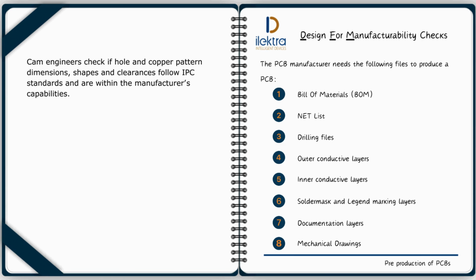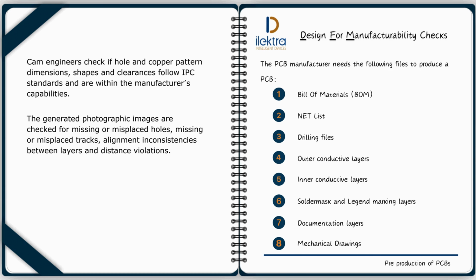Upon receiving those files, the CAM engineers check if hole and copper pattern dimensions, shapes and clearances follow IPC standards and are within the manufacturer's capabilities. If not, they will inform the customer of any distance violations and provide solutions if possible. The quality of the PCB depends on the photographic images of its different layers. If those images are wrong, the process is doomed from the beginning.